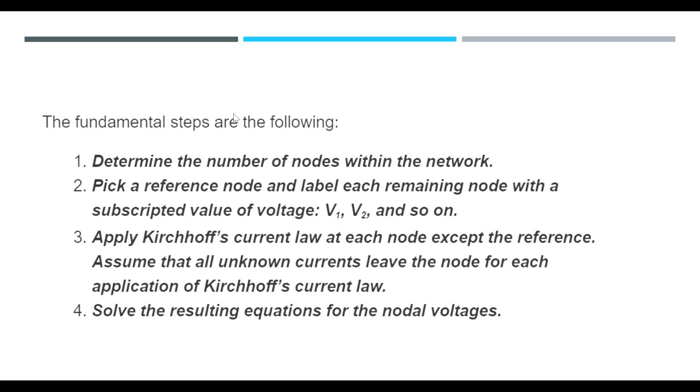The objectives are to be able to decipher the places where you can place a node or use a nodal point for your circuit. Also, to be able to successfully pick the references for the voltages that you want to use throughout your computation. Remember that the goal of a nodal analysis is to set up a system of equations where you can find the voltages and the currents throughout the circuit. Also, we want to review Kirchhoff's law for AC circuits, and of course, review how to solve the equations that you get from the nodal analysis.